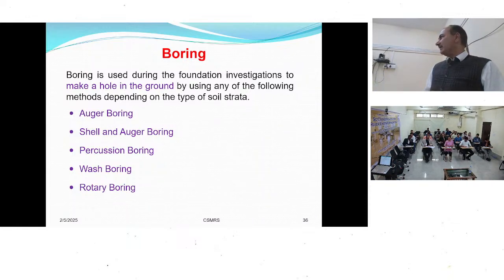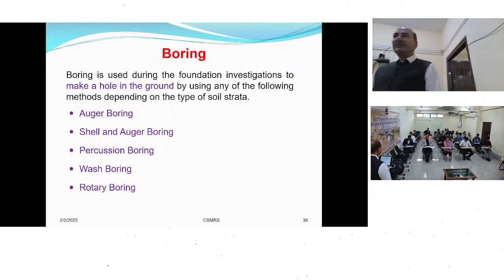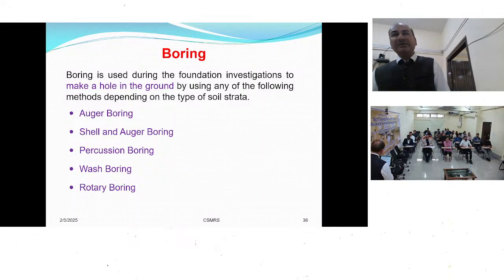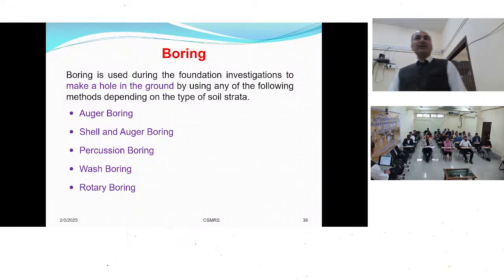So these are the different methods used for drilling: auger method, shell method, percussion method, wash boring method, rotary method. Now the question is which method you should use. Depending upon the strata, you will choose one of the drilling methods.